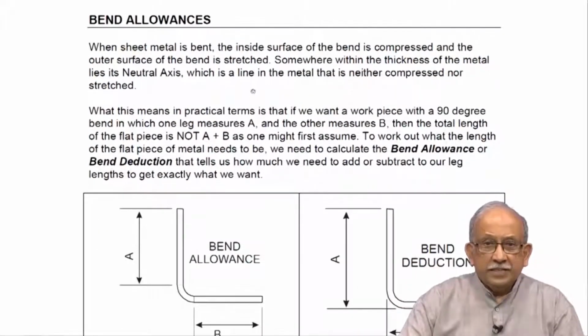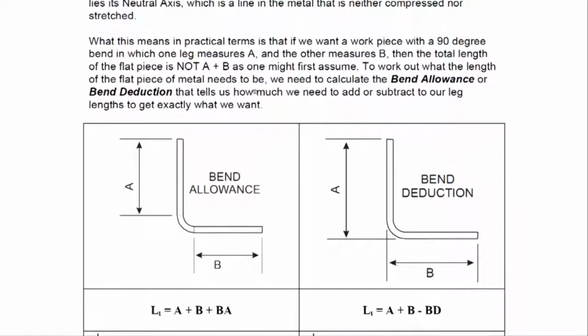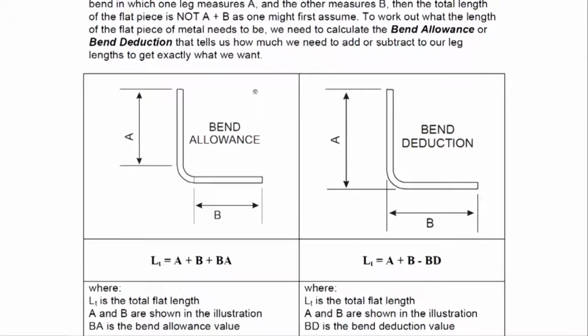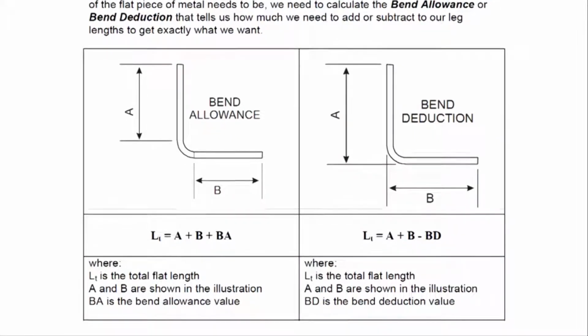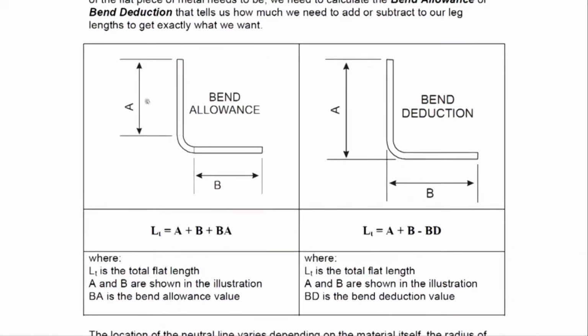So far the bending allowances which we have talked about are about taking the internal dimensions and adding something to it as a bend allowance. This is what we have been doing all along. Another way of doing it is saying in some cases we probably have only the external dimensions which are measurable. Alternatively, only the external dimensions are of interest to us.